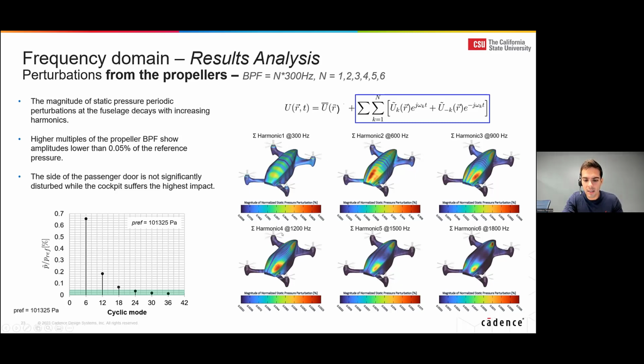In this case here, I can see that starting from 900 Hertz, this region gets pretty dark, which means if someone is getting in and out of this air taxi, the noise that someone would hear would not be in the high frequency spectrum, but rather in the lower spectrum, so a more grave noise, I would say.